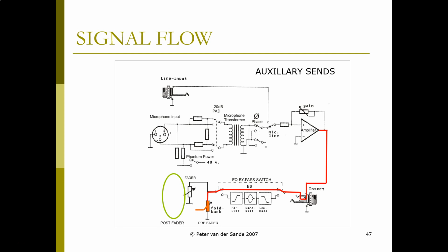After the fader, we have post-fader effects, which are the AF, after fader, and the PF, pre-fader sends. And the after fader sends are used for effects like reverb and so on. And again, this is a review from our last video. So we've got our blue signal, which is the after fader, and our red signal, which is the pre-fader outputs.